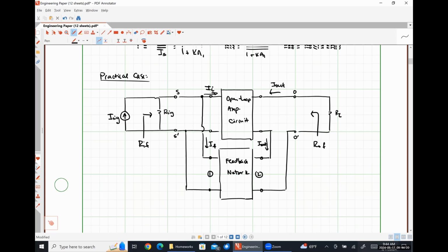So we have a diagram that looks incredibly similar to what we had for our feedback voltage amplifiers. So now we need to figure out effectively how our feedback network loads our system in order to apply the exact same process that we did with our prior amplifier. So I would like for you guys to go back to your notes and tell me what we did to find the resistance R22 for a feedback voltage amplifier.